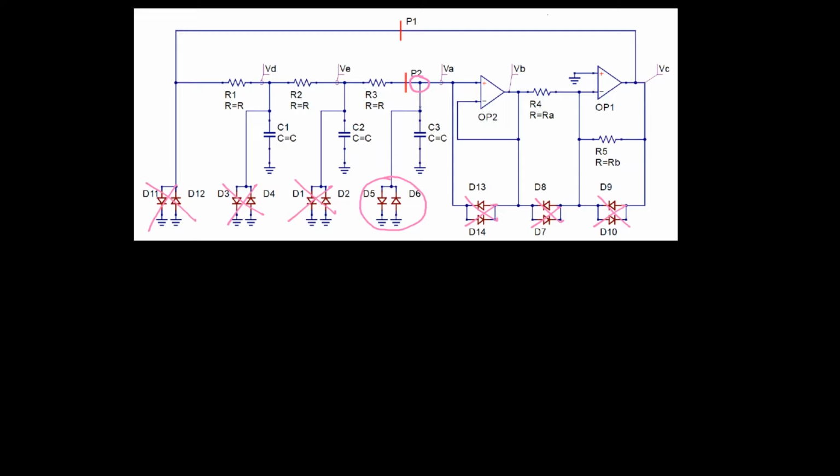And we know that when the voltage here is 0.7 volts, these diodes will behave as ideal voltage sources. So it will never exceed 0.7 or, for the diode in the opposite direction, negative 0.7 volts. That means that we also know that the peak-to-peak voltage at this node will be 1.4 volts peak to peak.